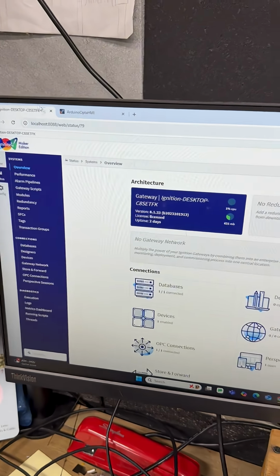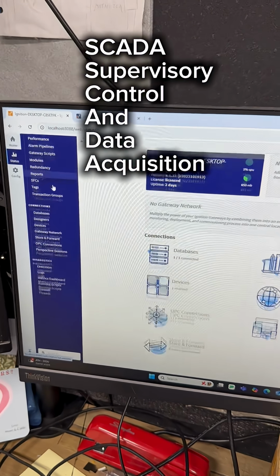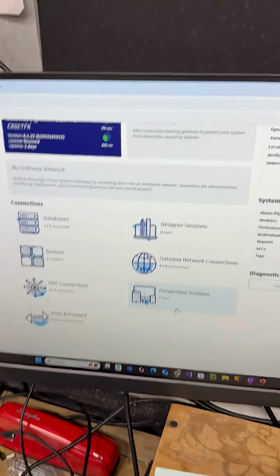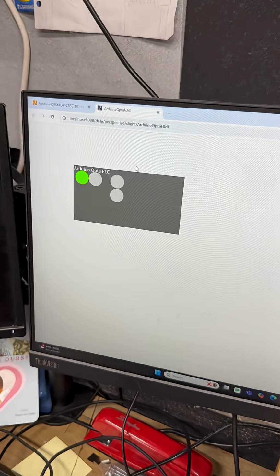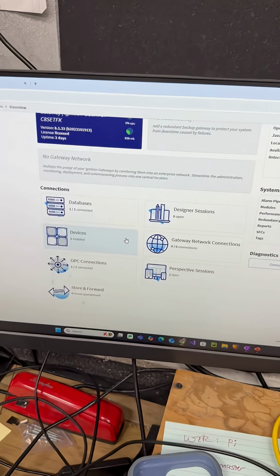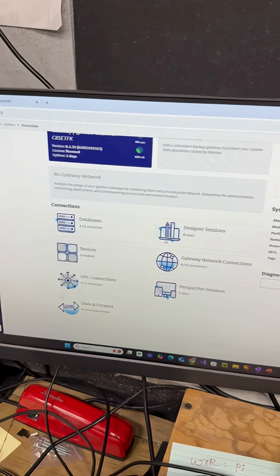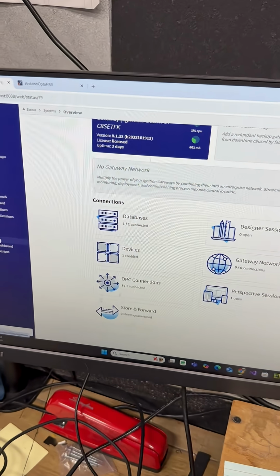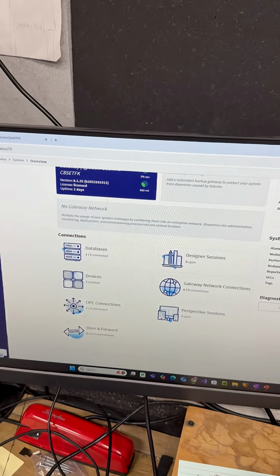Next up is the SCADA, or Supervisory Control and Data Acquisition System, and it's similar to an HMI because it often provides lots of graphics and screens like this Ignition software, but it also is an aggregate of data like Historian and SQL. It's also where you tie tons of PLCs and supervisory screens together, and it often has handshakes with higher level enterprise systems like MES or ERP.